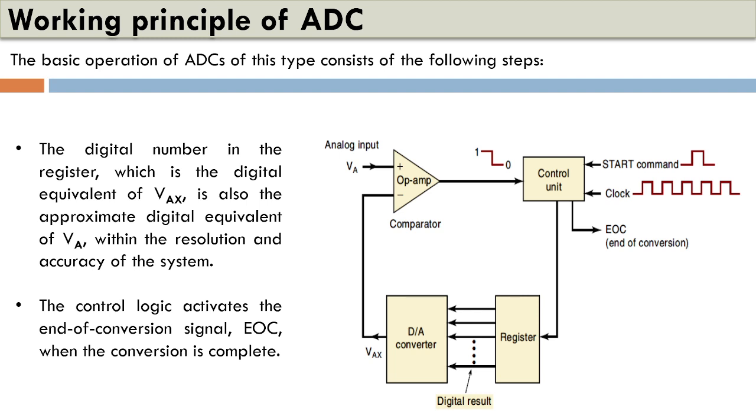So if a microprocessing unit is monitoring the conversion of the ADC, it will be a wastage of the microprocessor's resources, because the microprocessor will sit idle for a pretty long time. So what the microprocessor can do is initiate the conversion process and start working on its own functions, or handling other resources.